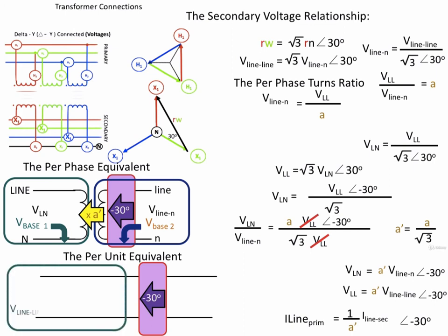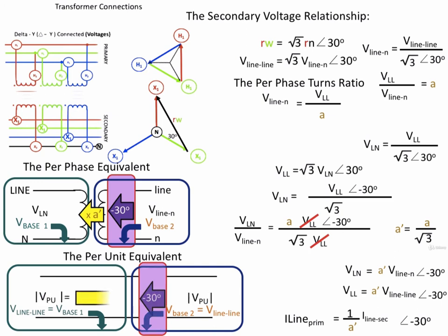And the two zones are still there. You can have the phase shift operator in any one of the zones. It doesn't matter which one you pick, because the magnitudes of the voltages going from the primary to secondary are still going to be the same. They're equal, as are the magnitudes of the currents. It's just the voltage phase shift that you have to worry about.